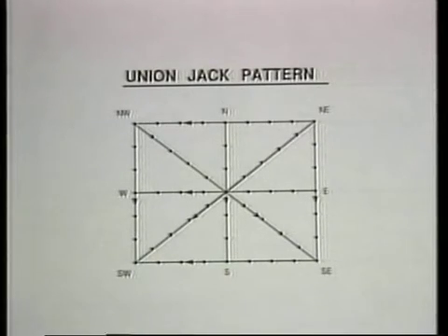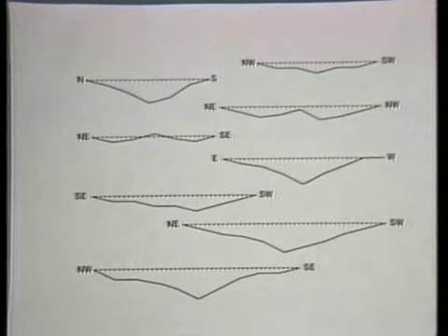Compass points are often used to help identify particular measurement paths. In this nomenclature, the diagonals would be the northwest to southeast path and the northeast to southwest path. Observe that the measurements along the diagonal and vertical paths are made from north to south, and that the measurements along the horizontal paths are made from east to west. Note also that the proportions of the short side, long side, and diagonal are 3, 4, and 5. Furthermore, to ensure profile intersections always occur at data points, the minimum number of sampling segments on the short side is 6. Before the profiles are joined, each profile is adjusted so that its endpoints are 0.